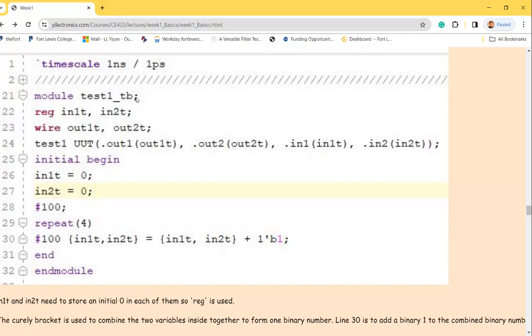I can repeat the question. We only have one clock source, but you can divide that clock for different frequencies. So, for example, I have certain names of the ports. They are specific hardware available on the FPGA, okay? And I have to claim them if I want to use the FPGA as a test bench. So it's going to be a parenthesis that has clock, switches, push buttons, like the seven-segment display, the display ports, the decimal point ports, or something else. So there will be ports for that test bench, but here it is a simulator, so we don't need the ports. It's just everything being provided by the computer.